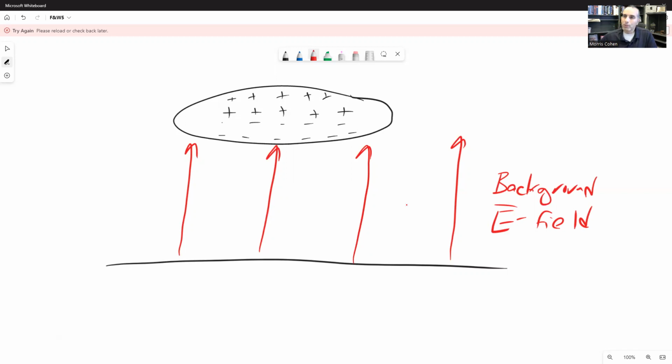And eventually, if it builds up high enough, you'll get a spark, right? A spark, just like if you rub your foot on a floor and then touch a metal doorknob, you'll get a little jolt and a little spark. And it takes a certain voltage, a certain electric field to break down air and convert it into something electrically conductive. And that's what a spark is. And once you get this spark, it has a way of self-perpetuating that I'm about to describe.